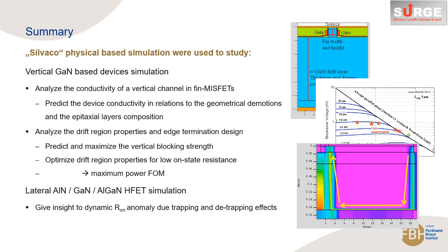And for lateral aluminum nitride GaN AlGaN devices, we have used the simulations to give insight to dynamic on-state resistance anomaly due to trapping and detrapping effects.